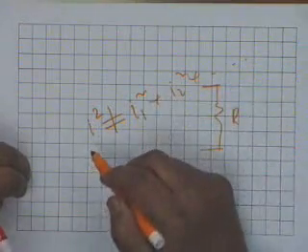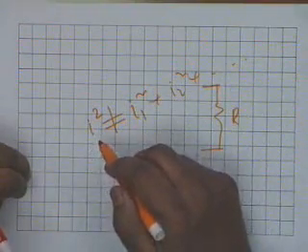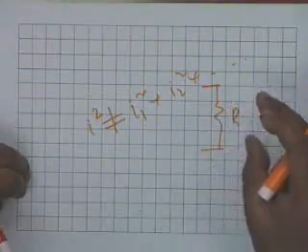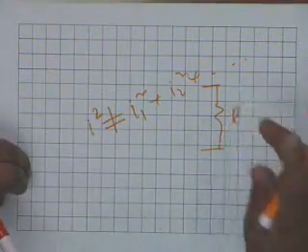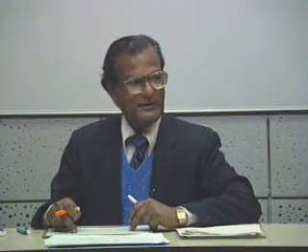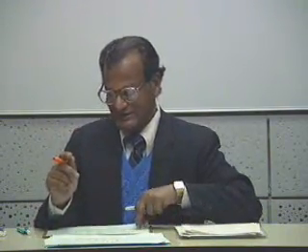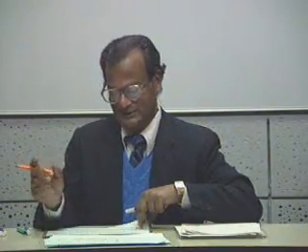Alright, that's the reason. Superposition does not apply to relationships which are not linear. Voltage is IR or current is V by R, and therefore you can add V1 and V2 and obtain the result. Now this mistake is very often committed by students. Power, energy, cannot be obtained by superposition. It is only voltage or current.